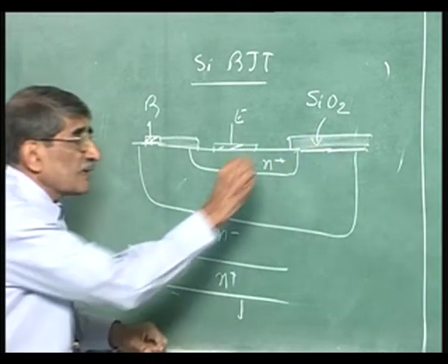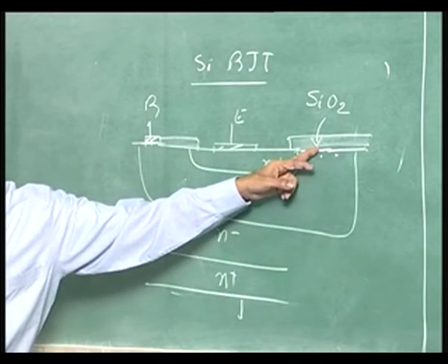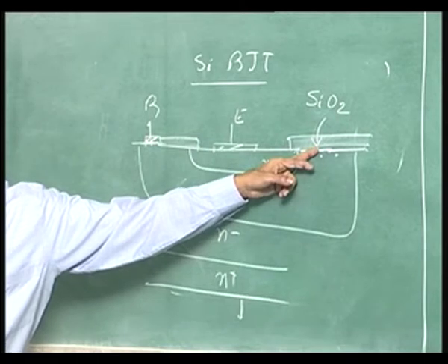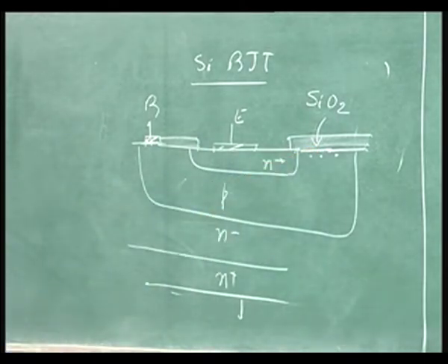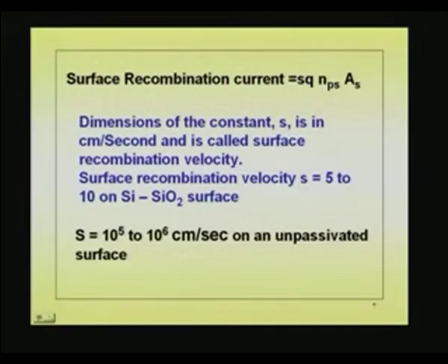In fact, whatever bulk concentration is here nearby diffuses into surface to recombine there. So, what we said is the surface recombination velocity, surface recombination component is the one that we are talking of. So, just like the bulk recombination is proportional to the carrier concentration, the recombination at the surface also is proportional to the carrier concentration, Np near the surface, just adjacent to surface. So, it is a per centimeter cubed, okay.